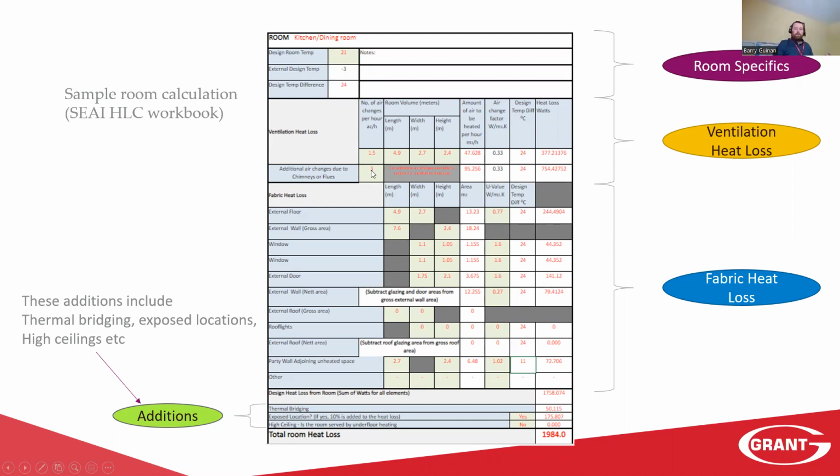We would also possibly block up the chimney or get rid of the open flue. So this then would go to 0. So straight away, you could possibly shave half of the heat loss from this specific room. So it is important to factor in all the different bits and pieces and see how we can reduce these values.